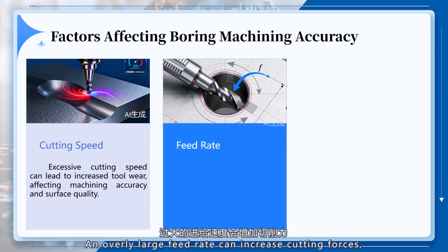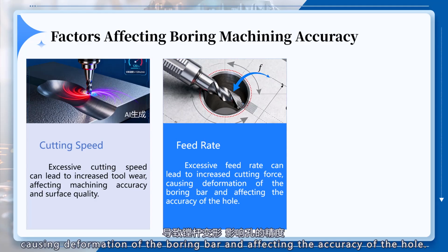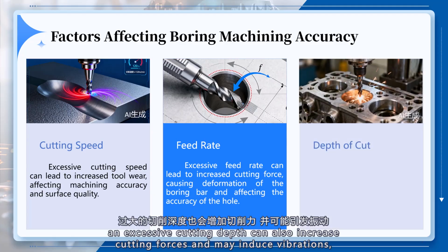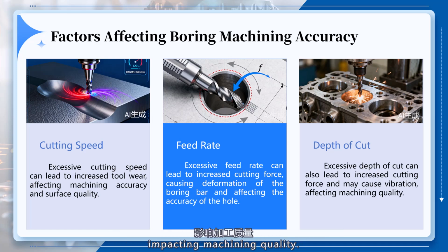An overly large feed rate can increase cutting forces, causing deformation of the boring bar and affecting the accuracy of the hole. Similarly, an excessive cutting depth can also increase cutting forces and may induce vibrations, impacting machining quality.